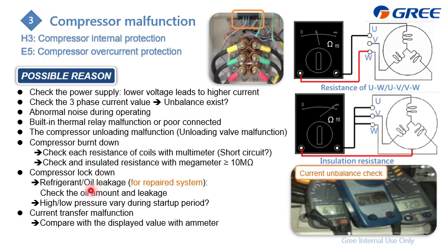So you need to check whether the oil can flow back to the compressor for lubrication, especially from the oil separator. And for the refrigerant system, we're just afraid that maybe there's some blockage, which when the compressor operates leads to a higher delta P, and higher delta P indicates it will cost more power to operate, and higher power always means higher current.